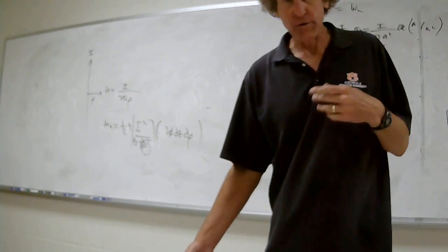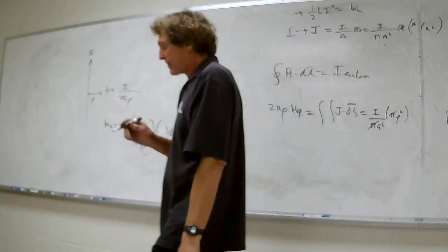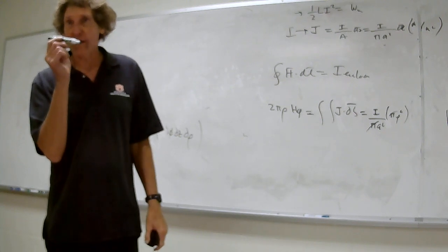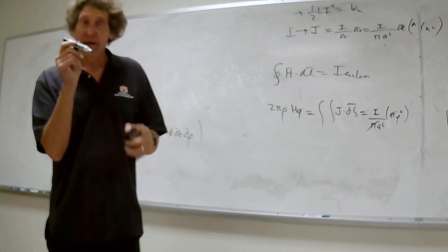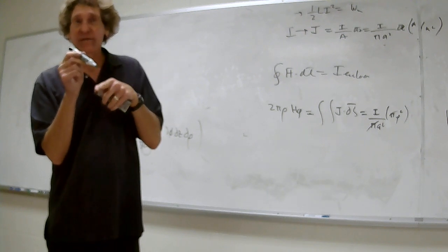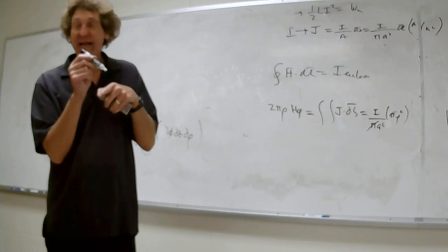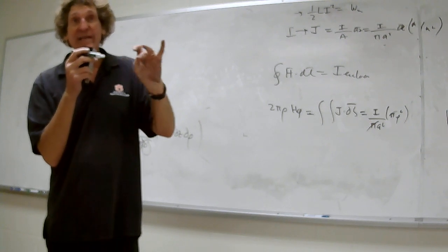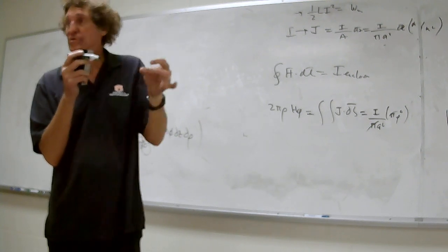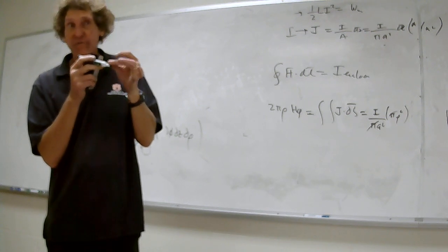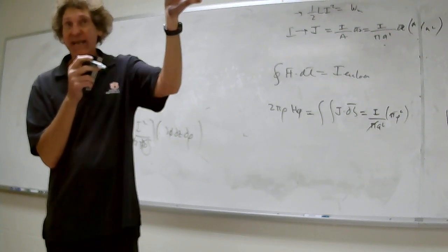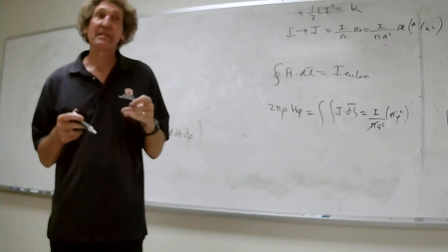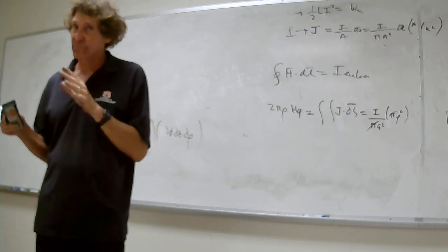So, a good question you should be thinking of is, well, if I know I've got a wire, and I know what the internal inductance of that wire is per meter, that's true. Well, how do I get the external inductance? This is something you're going to get a little later, but it has to do with partial inductance. So now what we have to do is we need to know something about the closure of the path. And once we do that, then we can get an estimate for the H field or B field in the vicinity of that loop, and we can therefore estimate this. I'll talk about this more later.